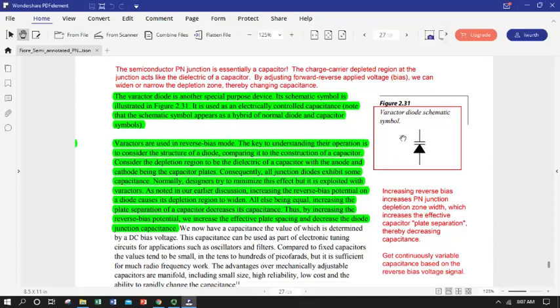If you all took AC circuits, you probably came across the concept of resonance, where we had to have exactly the correct capacitance and inductance combination, and we got this very high or very low impedance in our circuit as a result. Putting in one of these variable, solid-state capacitors allows us to tune a circuit to achieve resonance.